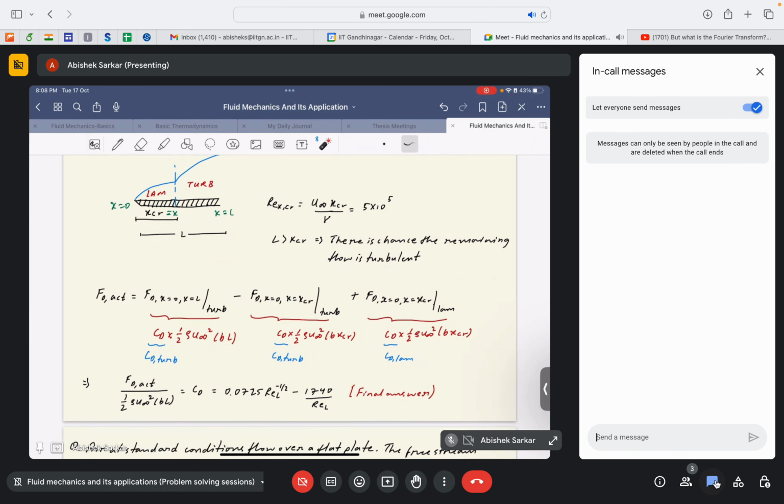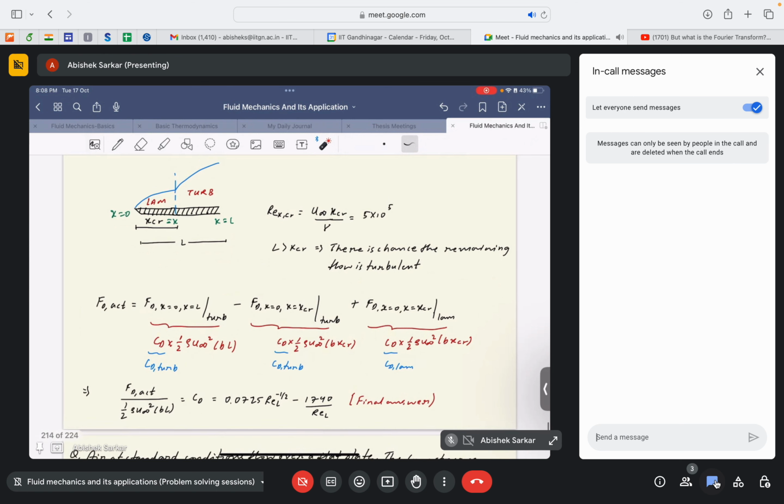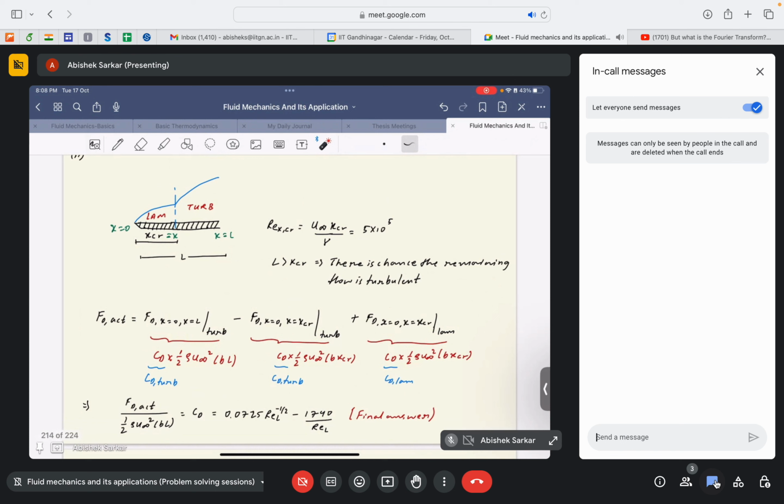Now this part is difficult. The boundary layer theory doesn't specifically tell us how to evaluate the drag force if you are starting from an arbitrary point of the flat plate. By default, it assumes that the initial point that we choose for determining the drag forces or the shear stresses is the leading edge. The calculation is taken from the leading edge of the flat plate.